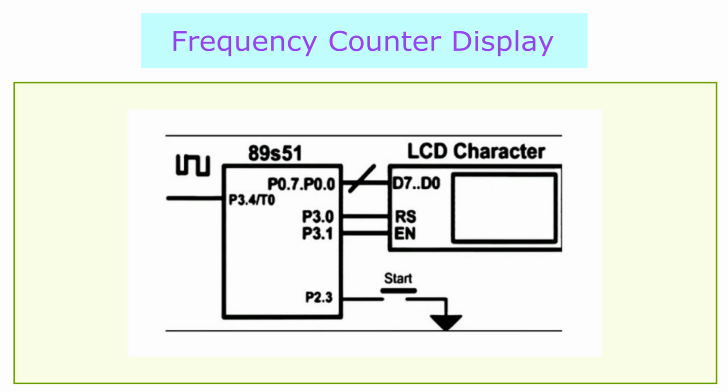Period measurement is done by measuring the time required for an integer number of cycles rather than counting cycles for a constant gate time and dividing that time by the number of cycles. At high frequencies, a frequency counter uses a prescaler that reduces the frequency, which helps to read the output.